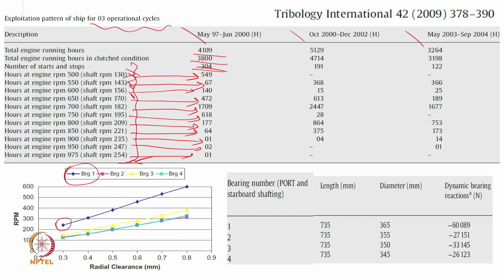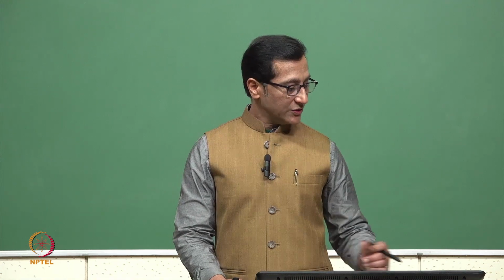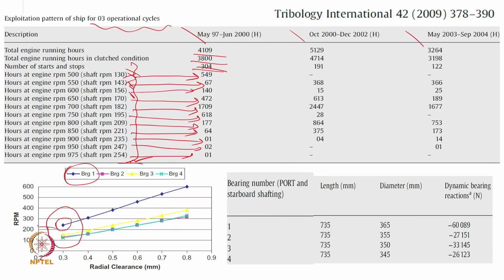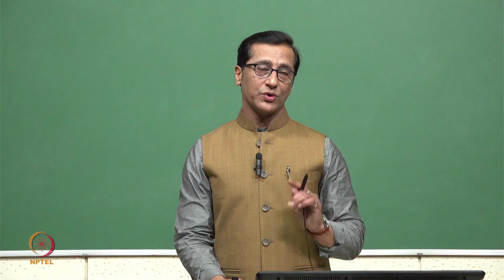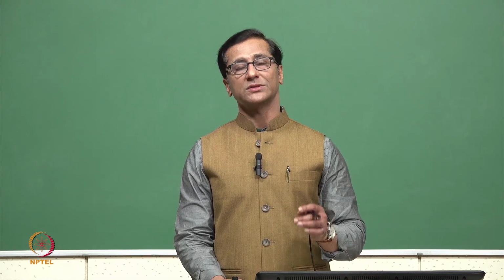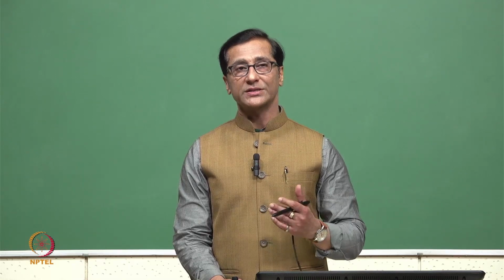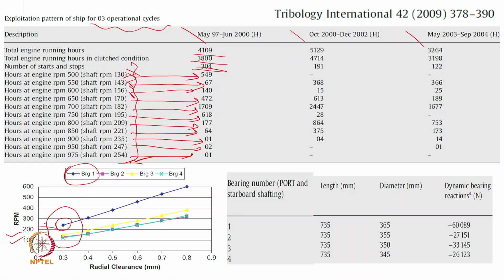However, that doesn't happen, and that's why we need to increase the overall idling speed of the shaft, because they have to have an idling speed. Instead of going for 100, if the speed moves to 200, that bearing failure will stop. Bearing failure will be almost negligible. But because the idling speed is on the higher side, it may cause some more losses in the engine, or say friction in the operating cycles. So overall, there should be a trade-off.